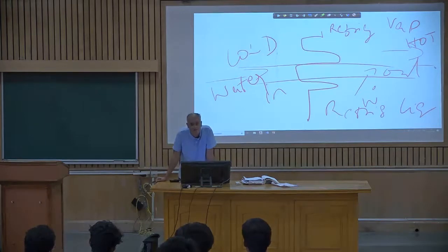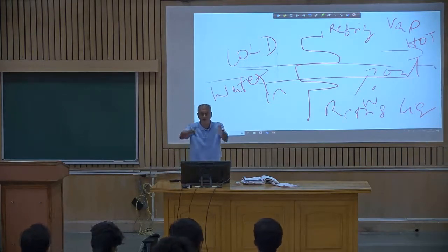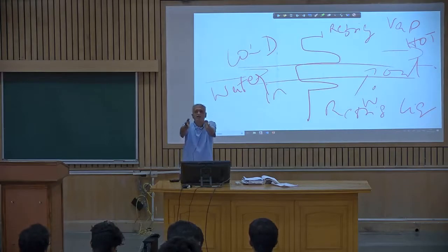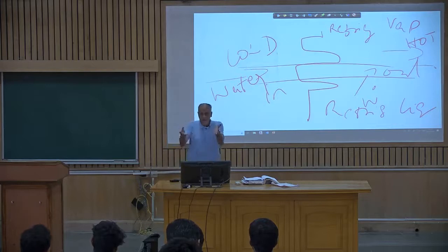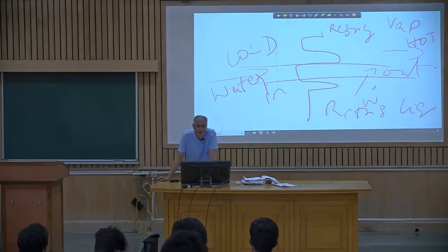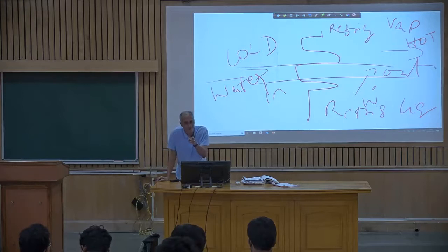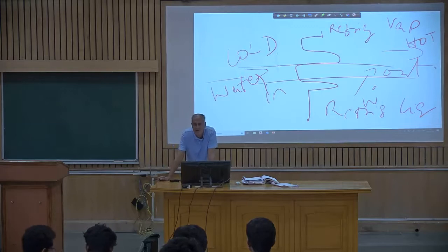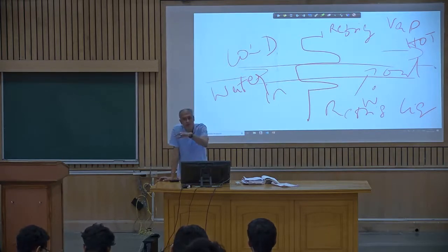Change in temperature, interfacial temperature, you're talking about water and refrigerant coming and making contact, right? So we actually measure the interfacial temperature changing with respect to time with the real instrument for 2 minutes. And then from the slope, I can tell you whether the kappa is high or kappa is low. But it's not just kappa, there is Cp also there, correct? So I do some calibration and get rid of the Cp change. So I will give you a thermal conductivity, right? Exactly what you're talking about. We bring both in contact and we measure the interfacial temperature change with respect to root of time because that's the solution for the unsteady state.